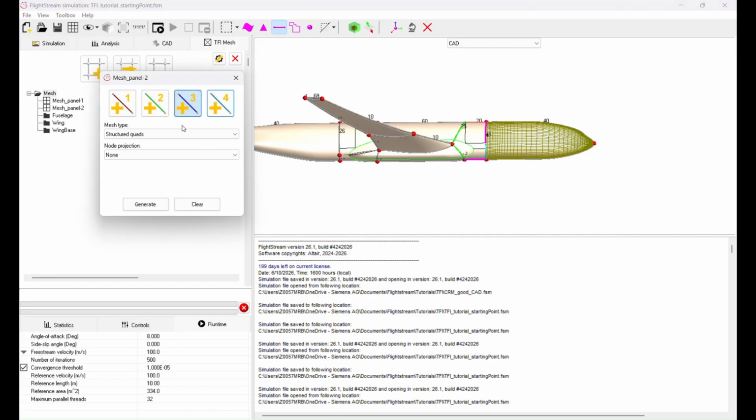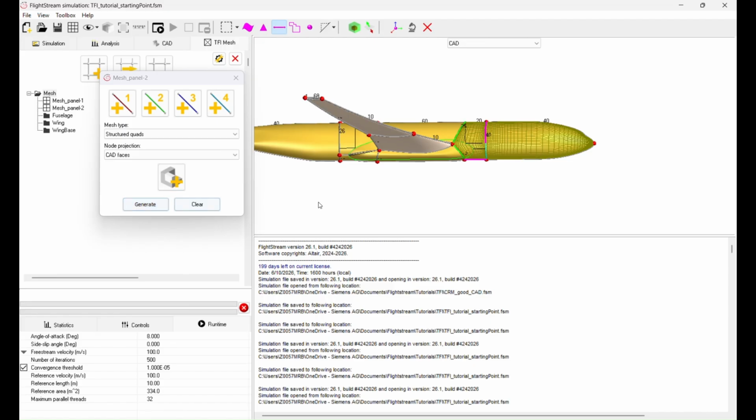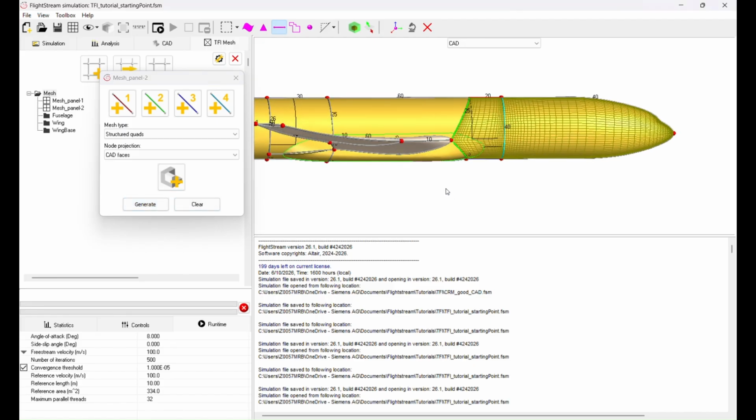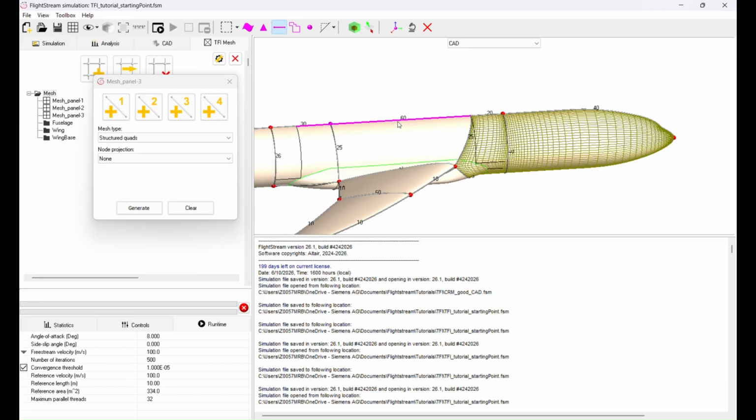Make sure to go either clockwise or counterclockwise and do so consistently within each panel. It doesn't matter between different panels if you go clockwise or counterclockwise, but for the mesher to work properly, you need to have it such that the curves are selected in a consistent order.